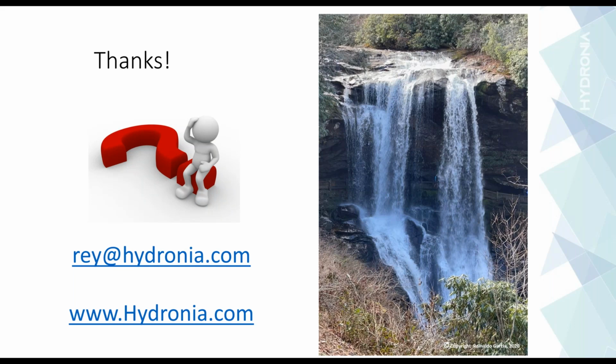Second question, can the model consider variable bed granulometry and its evolution in time? For example, bed armoring. Well, the version that we are releasing in the next month or so, 8.05, will include the active layer.